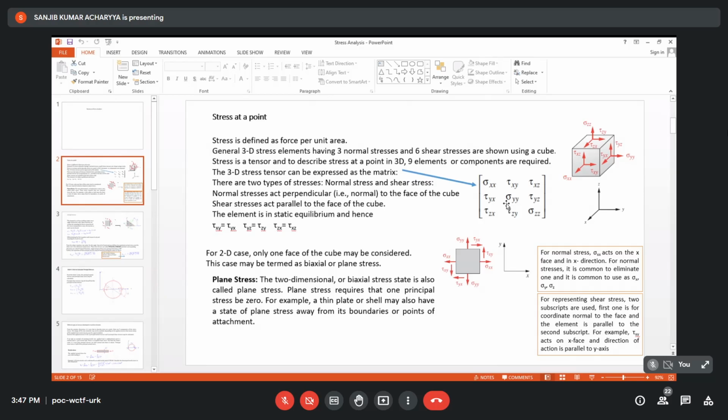Yes, sir. A design is to be done. I know the given performance or system. From there, first of all, I have to identify the load, by force analysis. Suppose it is a problem where this is the member and these are the external loads. Now tell me, what is the load upon this particular link? The link is a part in the system. To what forces is this link subjected? This is an expertise. As a designer, you should have this expertise, force analysis. Am I clear? Yes, sir.